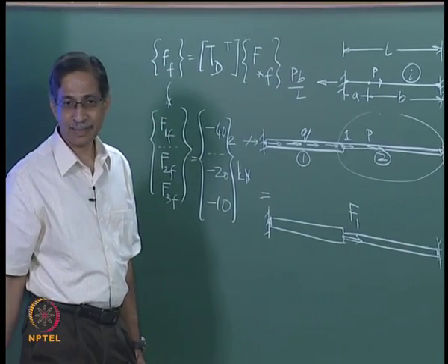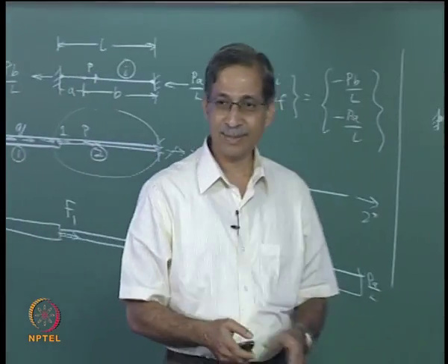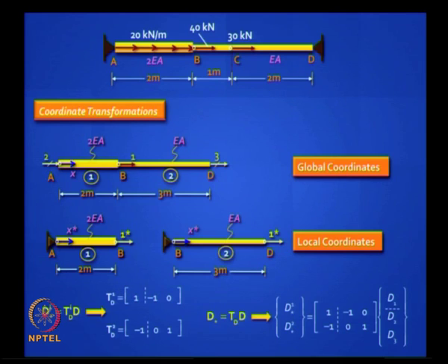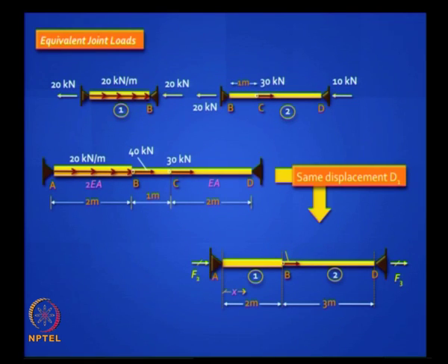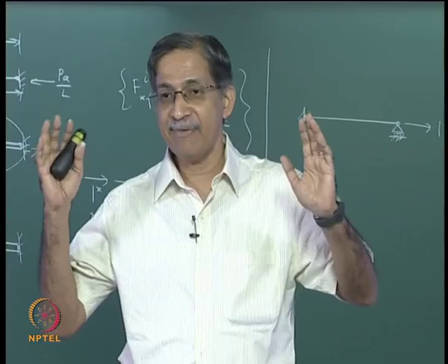Now remember, there was a nodal load in the structure. Let us go back to the original. Remember, there was a 40 kilonewton acting at F1. So that you have to include. So you have to do it the good old way, and you will write it like this. So this is what we discussed. Manually do it. You will end up with the same displacements as you would get in the original structure, but now you also have to add FA, which is already there, so we will use that later. Finally, your net load vector is FA minus FF.